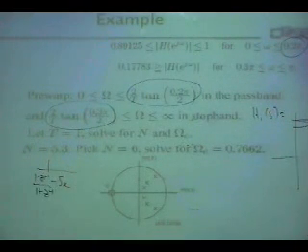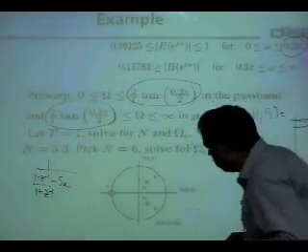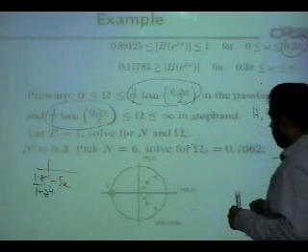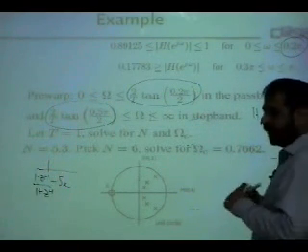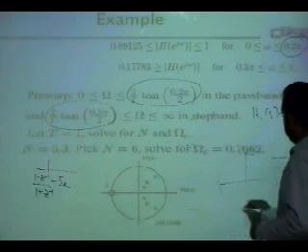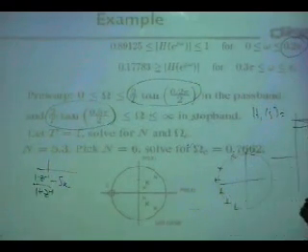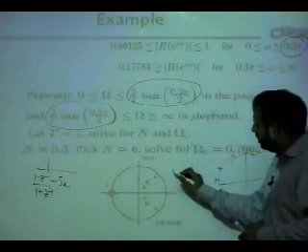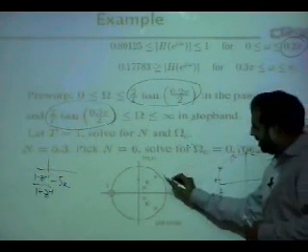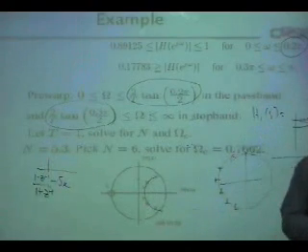In the analog domain or S domain, all the poles will be placed on that omega c circle? Yes, guaranteed. All the poles will be on the omega c circle, something like this. Okay? And that's why once you design a Butterworth filter, you will find even in Z domain, the poles are placed on a circle.